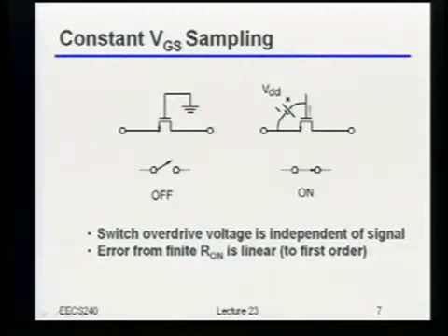And then when I want to turn the thing on, rather than just tying this to VDD, I always tie the battery from the source to the gate. In other words, I try to maintain a constant voltage from the source up to the gate. Conceptually, this actually works beautifully well. Now, why is this kind of a pain in the butt? Or what's sort of annoying about this?